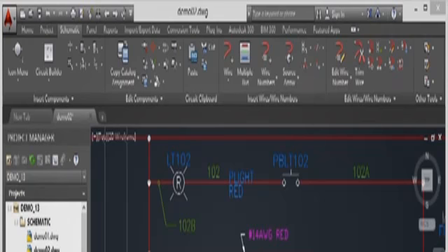It's actually a little bit easier to select them individually, I find. So I'm going to go for 1 and 2. I want those two attributes to move. I then press enter to confirm, and then it'll ask for a base point. Now you can use your dynamic input if you want to. So you'll notice there it's prompting me for a base point now.